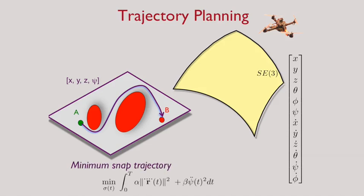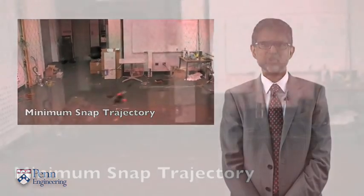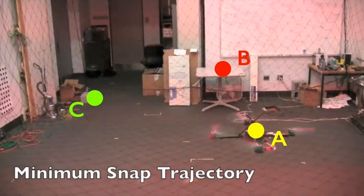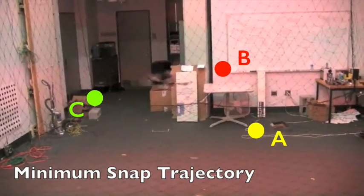So once we find smooth trajectories, and as we've discussed before, we prefer to make these trajectories minimum snap trajectories, we can then transform these trajectories into the real space with state vectors and inputs. And again, we're guaranteed that these state vectors and inputs will satisfy the dynamic equations of motion. Here's an example of a minimum snap trajectory that starts off at a position denoted by A, goes to the goal position denoted by B, through an intermediate point specified by C.